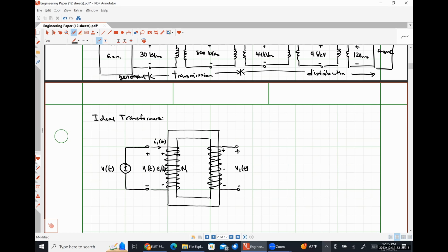Here explicitly, right next to the coil, I'll have my induced voltage, E2 of T. And then if I have any current flowing in my secondary, that'll be I2 of T. And then over here, I'm going to put a switch, and then some load impedance, ZL, like so.